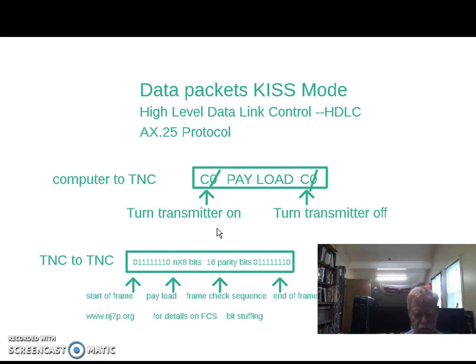And then we do something really special. We put 16 extra bits, we call them parity bits, that allow us to detect if there are any errors picked up in our payload. This is a very powerful feature because we can now detect errors of 1 in a million bits in this payload.